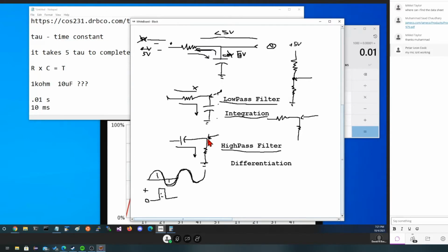Now you might say, well, so what? How could that possibly be handy? Well, integration and low-pass filters go hand in hand in that if I were building my own bass guitar and I wanted to emphasize the low frequencies, I would have these circuits all over the place. If I wanted to make sure that some high frequency things got through and not the low frequency stuff, maybe 60 hertz hum from a power supply, I could use a low pass filter to let the signal go through.